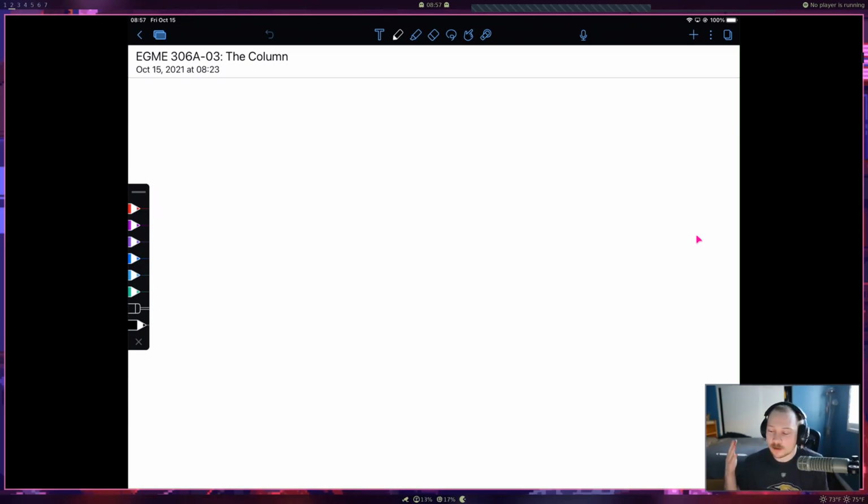Okay, so again, for this lab, we're going to have those different columns of varying lengths, and we're going to apply a compressive load to each column. And then we're going to see when it fails and how it fails. So short columns, as a little preview, are going to fail by yield stress, so it's a material failure. But our very long columns are not going to fail by material failure, but from stability failure. So they become unstable physically, and they buckle outwards, and that's why they fail. Okay, so we're going to start this off with a section talking about stability.